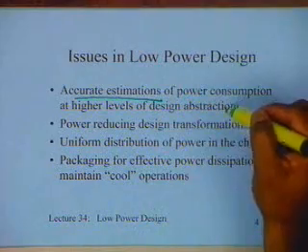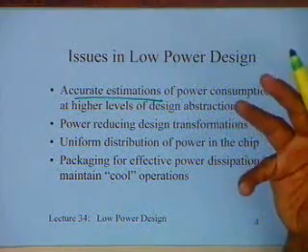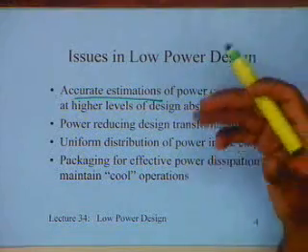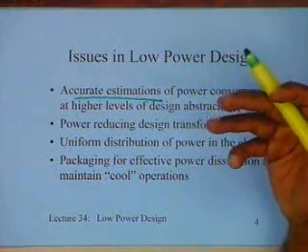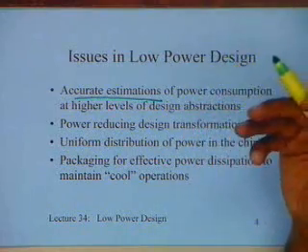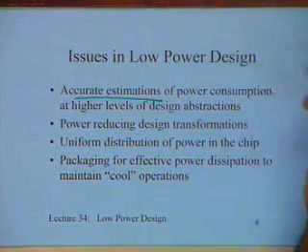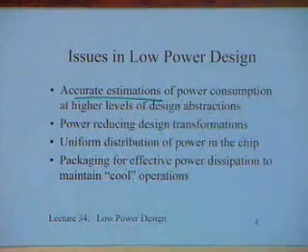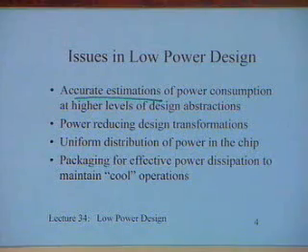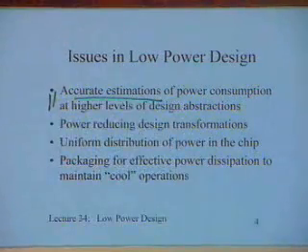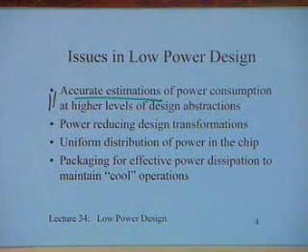But one is also interested in estimating, at a fairly high level of abstraction, what power is going to be consumed, because for all the optimization you will be working with a power budget, just like you work with an area budget and performance requirements. So you are interested in finding out what power is going to be consumed, and that is one area of work that people are doing. So you try to model and estimate the power.